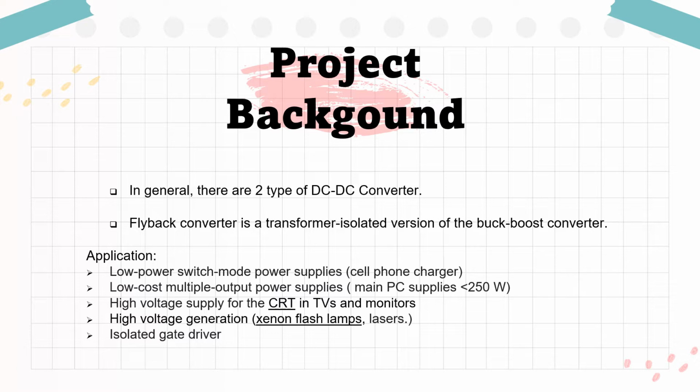The horizontal deflection drive for cathode ray tube used in television and monitors is often combined with the flyback converter. Flyback converter may also be used to provide high voltage for laser, copiers, and xenon flashlight. Flyback may also be utilized as a gate driver for isolated gate.